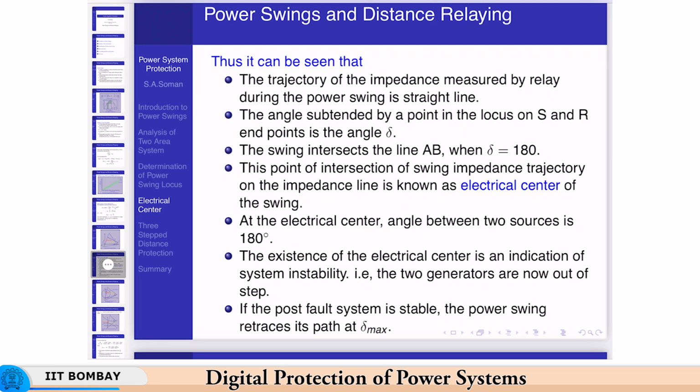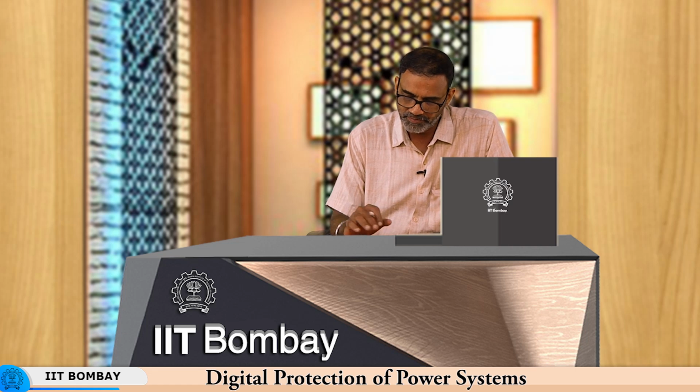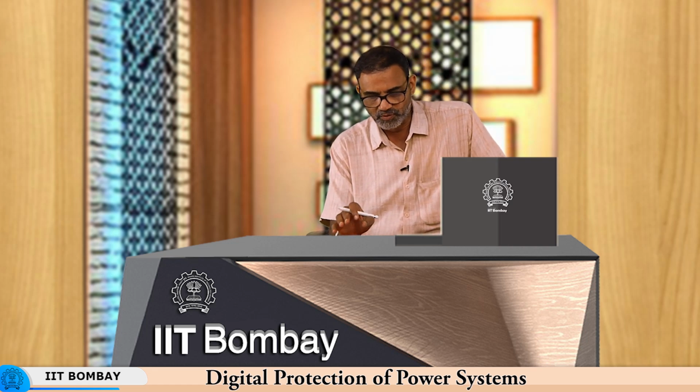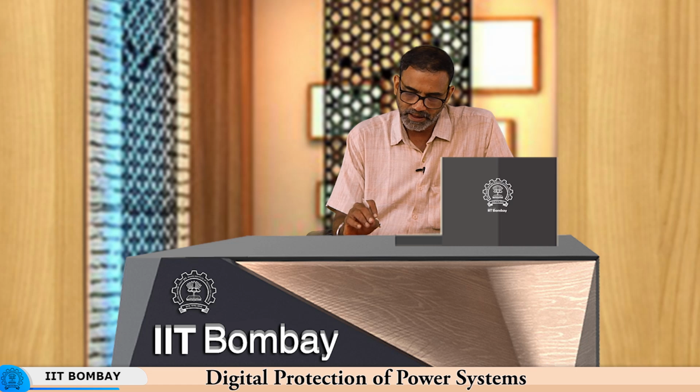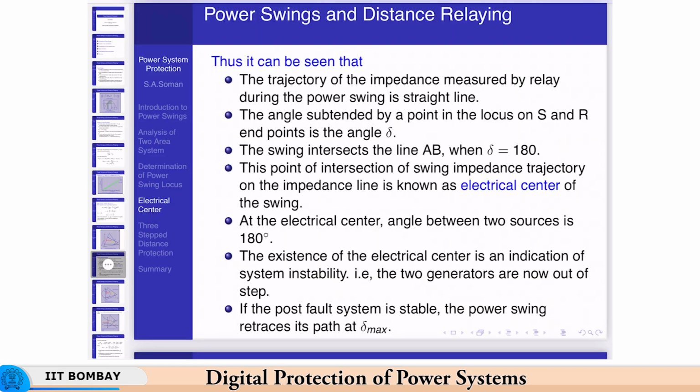This is exactly what we discussed: when the angle subtended by the locus on S and R and the endpoints is angle delta, and this angle becomes equal to 180 degrees, this is known as the electrical center, and it intersects the line impedance. Now, this, as we just discussed, is an indication of system instability. Okay.